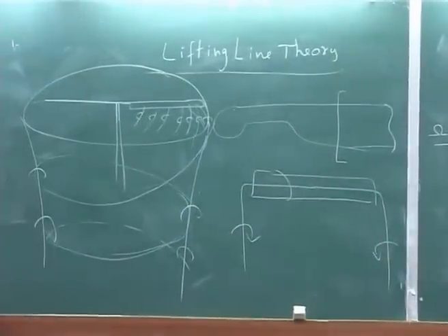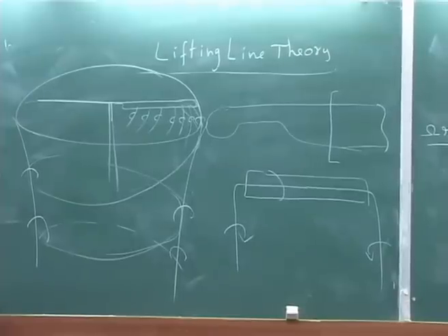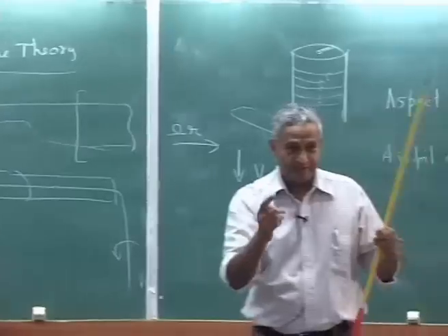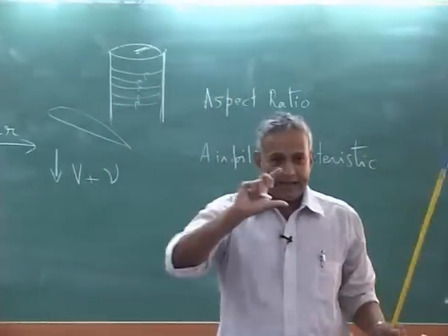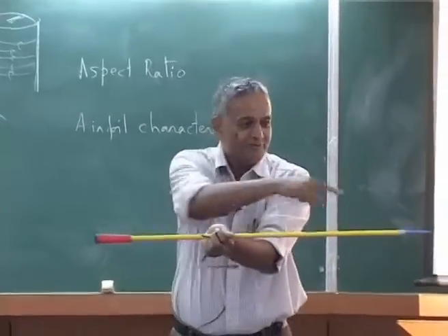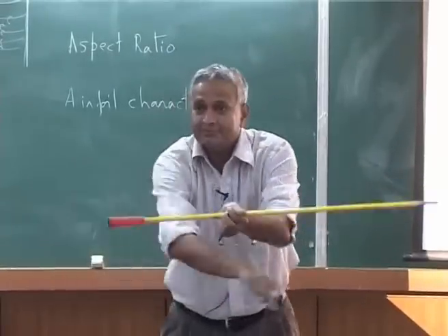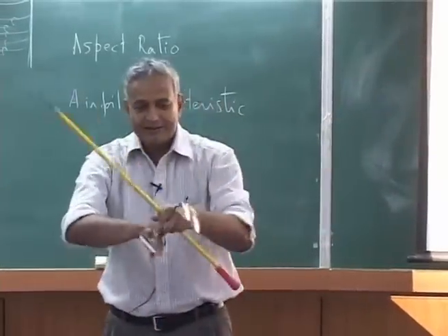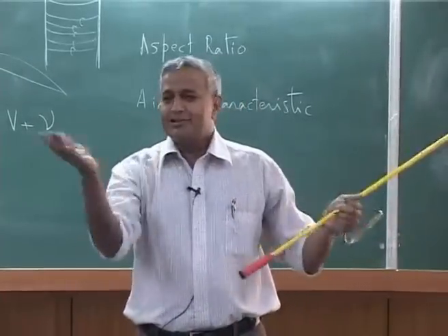Please understand, one blade gives a wake, it will come down, then there is another blade that will also give, that means there will be several helical wakes and there will be gaps between those wakes, because you get one coming down, then if you say another blade, that will come and they will go intertwined. But if you have infinite number, it is almost like a continuous cylinder.